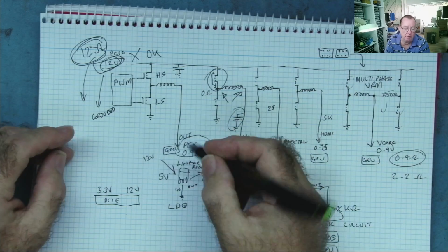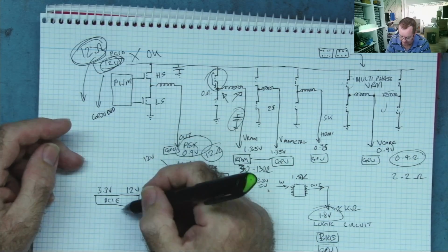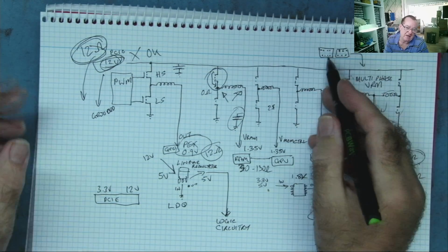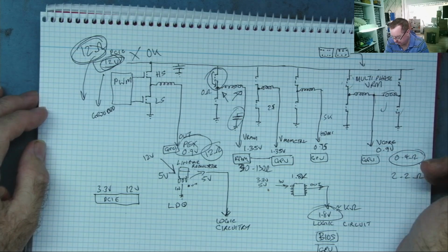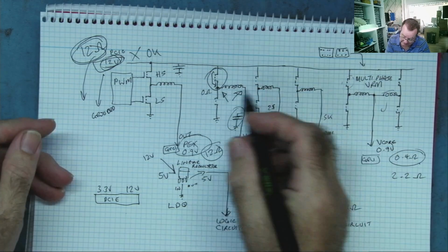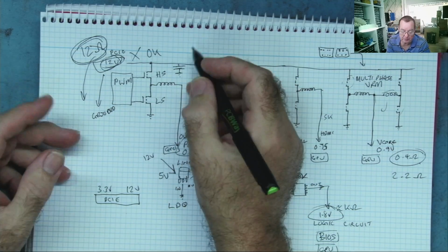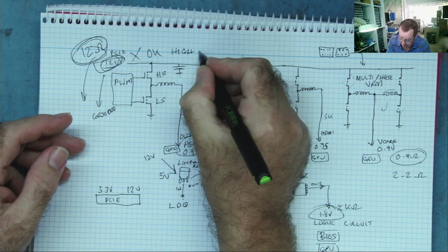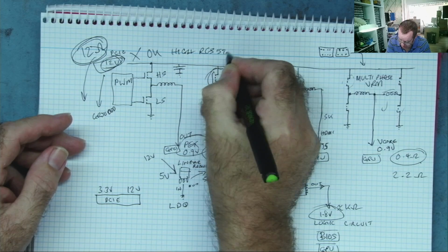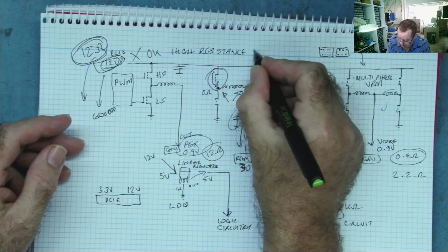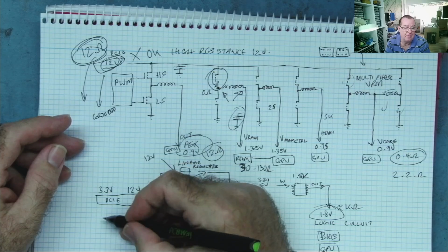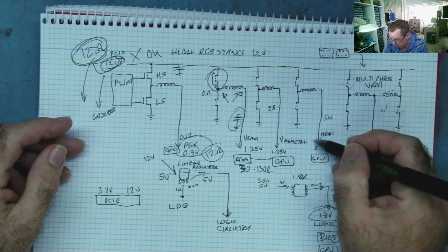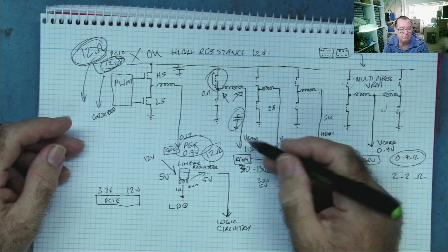So always when you're looking for shorts on the 12 volts, have a look both on the PCIe connector and on the 6, 8 way connectors on the graphics card, okay? One last thing I'll mention then is that you have this situation where we have a high resistance on 12 volts, both there and there, but you have a short on one of these voltage rails.